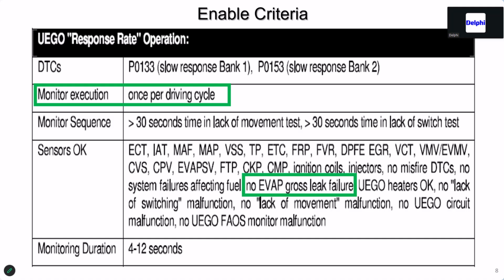Okay, and the last one at the bottom is important. When we start running monitors, drive cycle tests, the tests themselves don't take very long. I've seen 40 seconds. I've seen a minute on some. I've seen some Toyota early EVAP systems take an hour. But as a whole, when we run monitor tests, the actual test itself is only for a very short period of time because they don't want an intrusive type situation where the customer is going to feel what's going on.